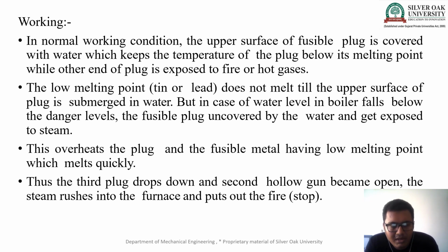The low melting temperature lead and tin do not melt as long as the upper surface of the plug is submerged in water. But if the water level in the boiler falls below the danger level, the fusible plug is uncovered by the water and gets exposed to steam, and the steam occupies the space.